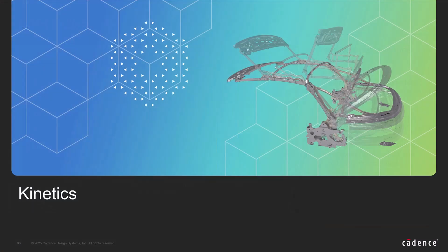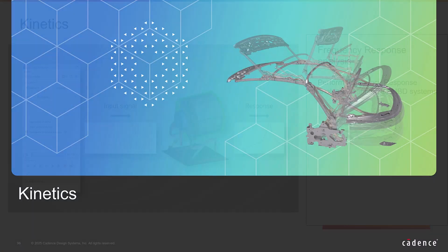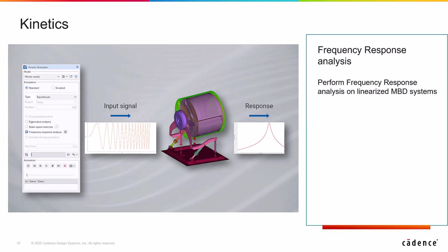Let's explore some updates in kinetics. The newly introduced frequency response analysis enables users to examine how the system responds to excitations at different frequencies. By applying an input signal, such as a swept sine force, you can evaluate the system's response, such as the displacement at a specific location, over a specified frequency range.